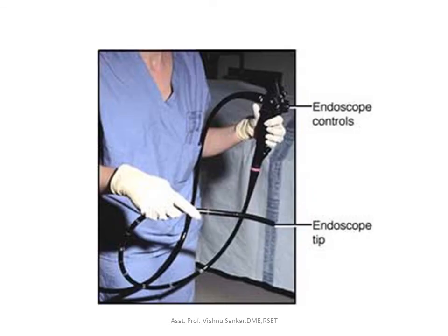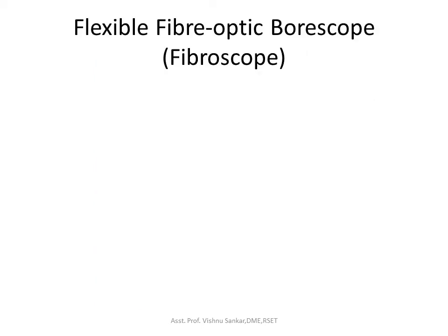Now, moving on to the most valuable NDT tool which is used for visual inspection. It is our eye. It is valuable because the eye has excellent visual perception. The sensitivity varies for light with different wavelengths. Under ordinary conditions, the eye is most sensitive to yellow-green light. For visual inspection, adequate lighting in the range of 800 to 1000 lux is of importance.